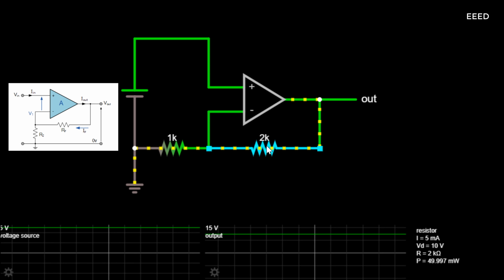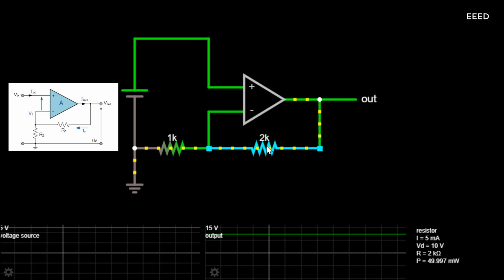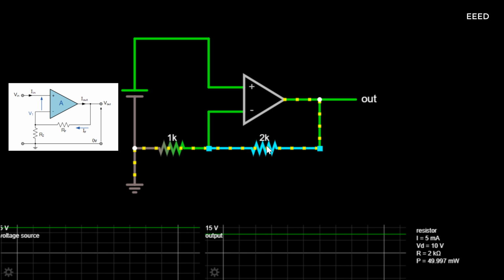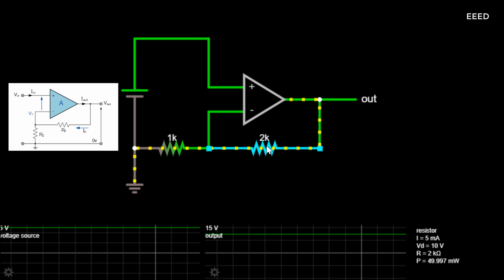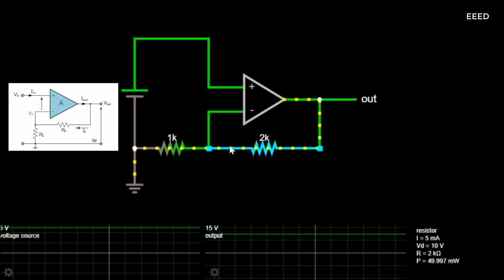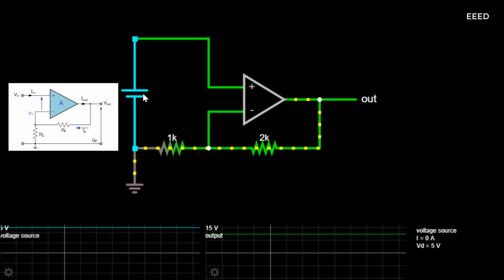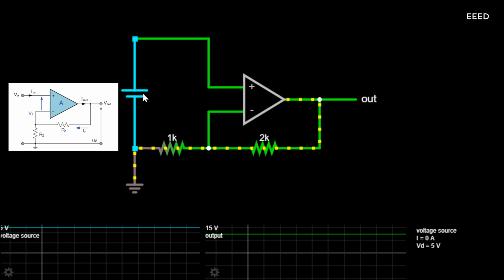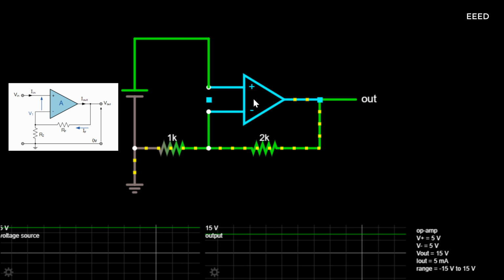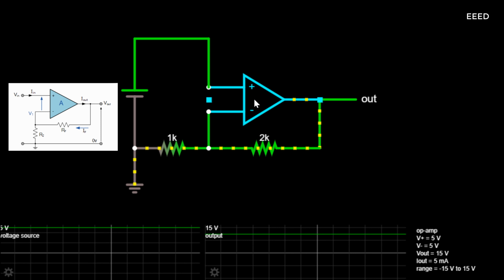In the previous inverting amplifier tutorial, we said that for an ideal op-amp no current flows into the input terminal of the amplifier and that V1 always equals V2. This was because the junction of the input and feedback signal, V1, are at the same potential. In other words, the junction is a virtual earth summing point. Because of this virtual earth node, the resistors RF and R2 form a simple potential divider network across the non-inverting amplifier, with the voltage gain of the circuit being determined by the ratios of R2 and RF as shown below.